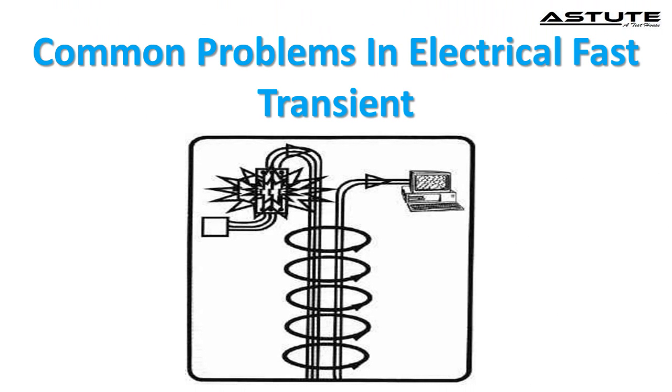Common problems in electrical fast transient voltage immunity of devices, given below. EFT pulses are generated by sparks on AC mains and occur whenever an electrical switch opens or closes, or when a motor commutator is running, powering up or powering down. At the moment of switching there is an infinite di by dt due to the variation in the load, due to lightning, because of capacitor switching.